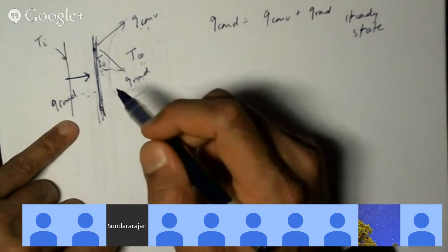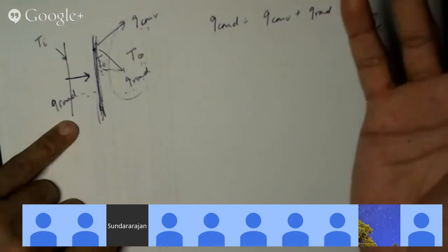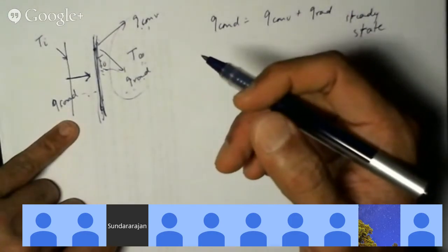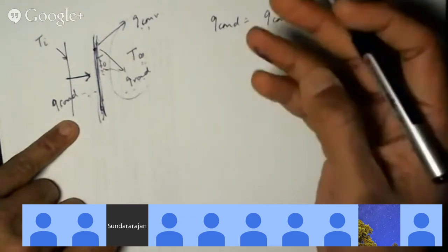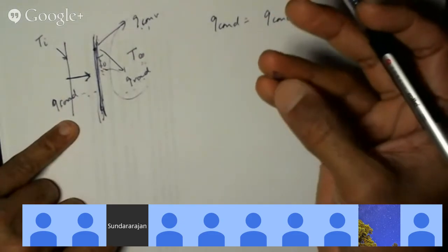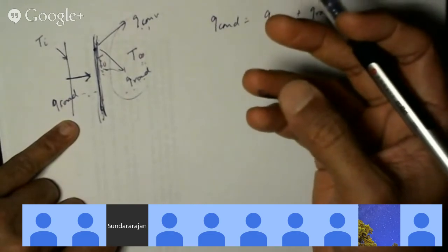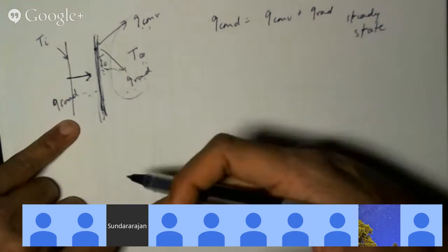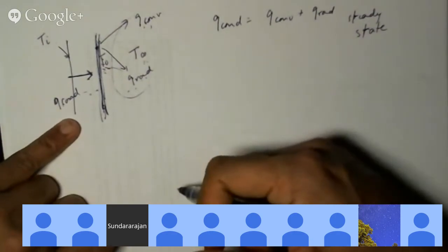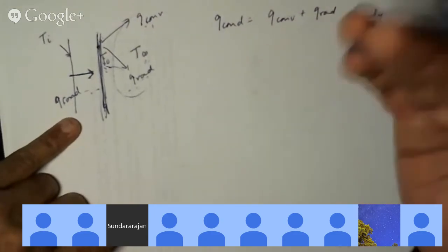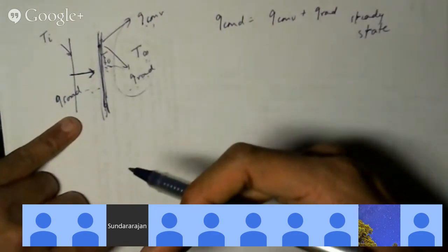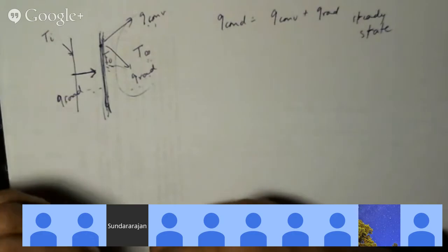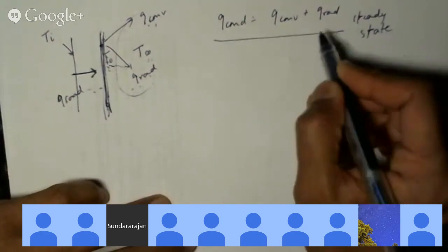If you stand in front of a stove, for example, a gas stove or an electric stove, you feel hot, correct? Why do you feel hot? Convective heat transfer? No. Radiative. There is convection going on too, because the gas will heat up the air, and the air comes in contact with you and heats you up. That's one mechanism. But the other mechanism is also direct heat transfer through radiation. So it's both mechanisms together. That's why you get that equation.